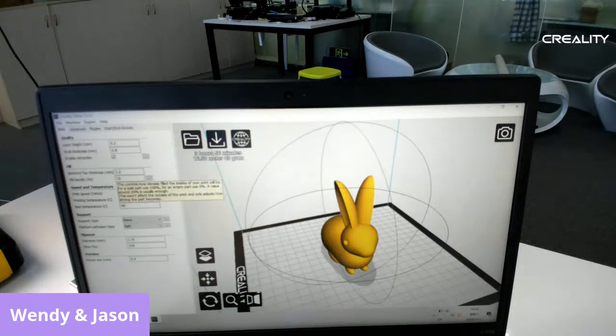And here's the option for the inside fill. Here the fill density is 10%. Personally, I would say that's probably a little bit too small. I personally would recommend 15, probably 20, depends. I would say anywhere between 10 to 20 is okay. It still depends on what you're printing and what you want to get. Here it shows the bottom and top thickness as well. And that's just the speed and temperature option.